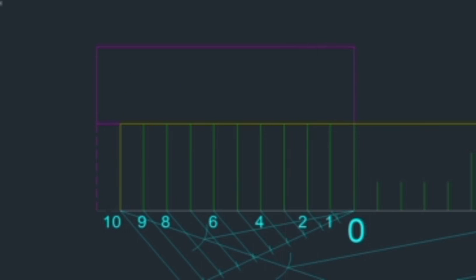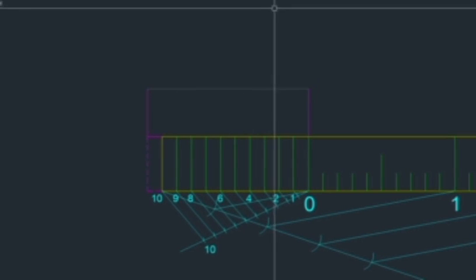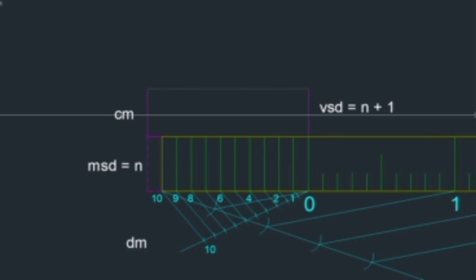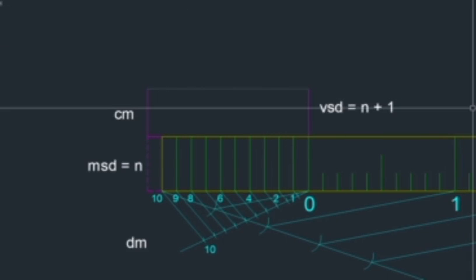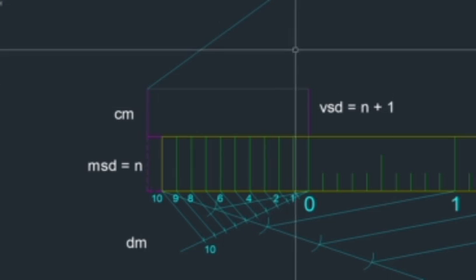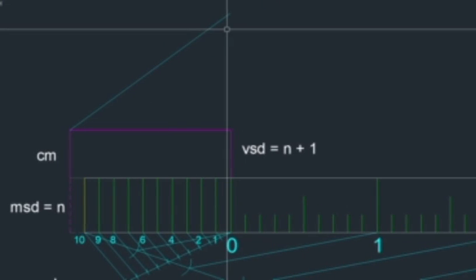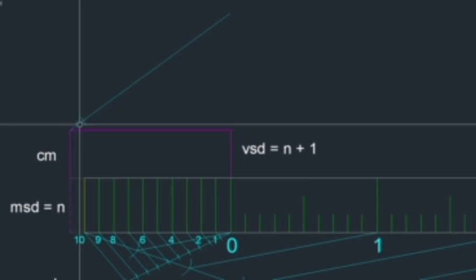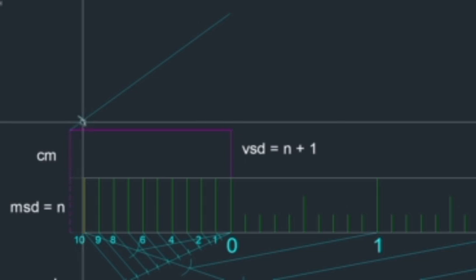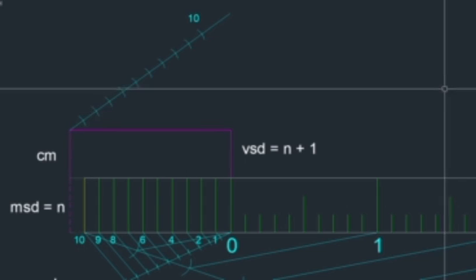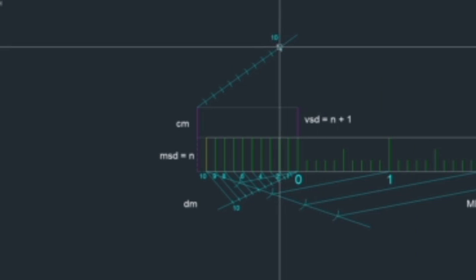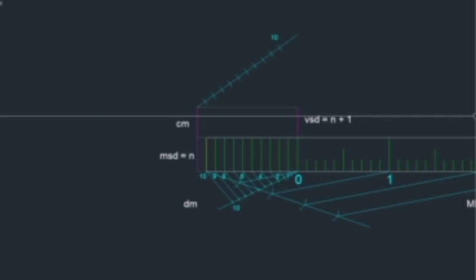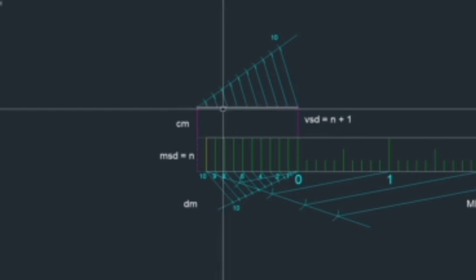This I want to divide into 10 equal parts. Similarly, as usual, I will make the drawings here. You put one line here. Okay. Then in the same way, whatever length you can take in your compass, similarly you can put 10 arcs here. So the last arc is marked here, and then you draw here, and then project all the parallel lines, and then project it here.